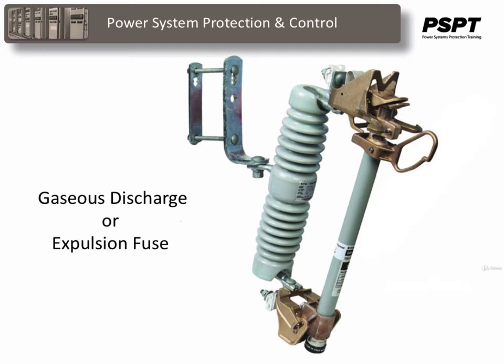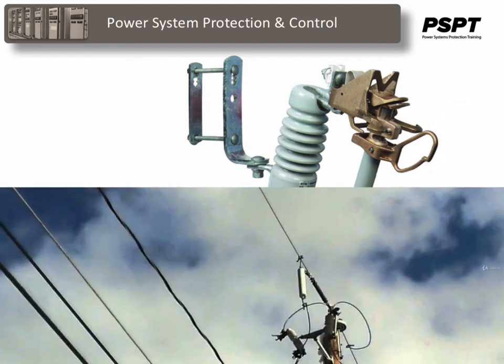Extending the arc increases the resistance, and the arc has less tendency to restrike. The blowing fuse produces quite a loud report or noise, and if this is objectionable in highly residential areas, a muffler can be used to reduce the noise and to catch the conducting arc products.